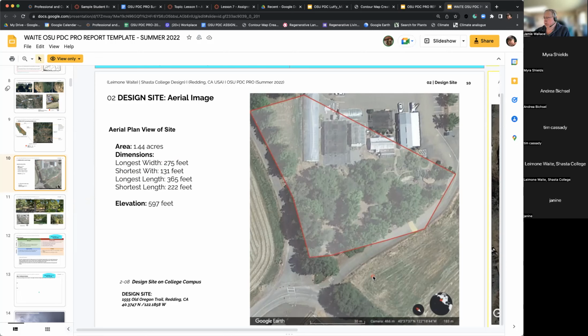Now, one thing I'll throw out here to everybody on the call, and I can see here you're not north up, just judging by this line here. So what you want to try and do, even though it might not visually agree with your senses, is to have north at the upper portion of the page. And that's a pretty firm standard in the landscape industry, even in the Southern Hemisphere.